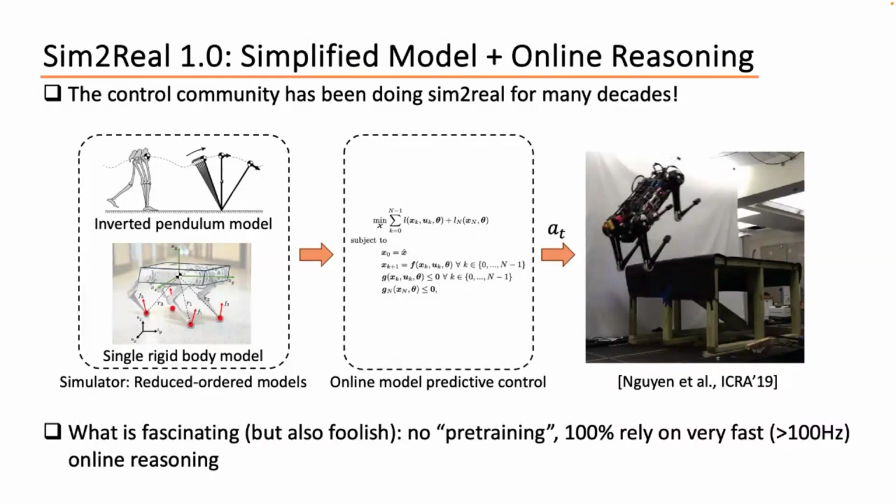Every time it encounters either a new or old scenario, it needs to resolve a big optimization problem to make it work. If you want to know more details of how to solve this, in general, for convex problems it's pretty straightforward, and for non-convex problems it could be tricky. It's why the control and robotics community spent a few decades developing efficient optimal control solvers. For example, you can do sequential convex programming, iterative LQR, DDP, whatsoever. But in general, solving this could be tricky.